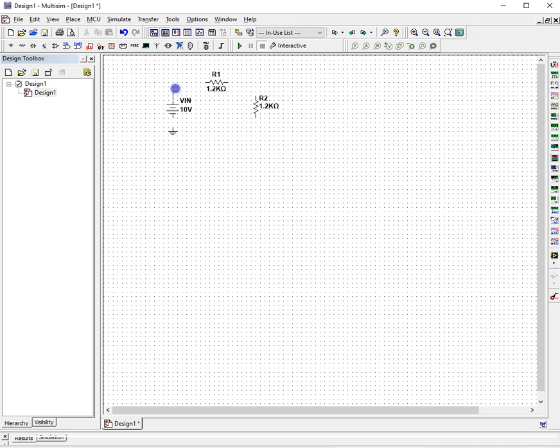To connect, you just go to the endpoints and drag the line. And then it is very important you have this ground, otherwise you're going to have an issue. And make sure you got this dot whenever you have three components. You can move this around and it doesn't look like a nice one.